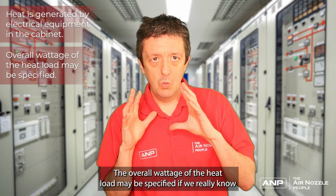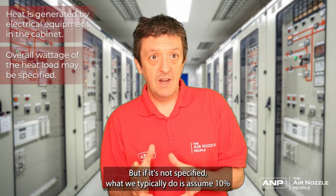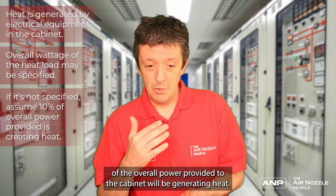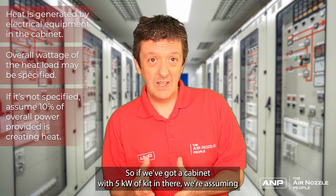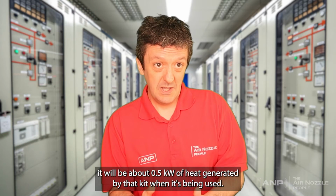The overall wattage of the heat load may be specified if we really know the equipment in there. But if it's not specified, what we typically do is assume 10% of the overall power provided to the cabinet will be generating heat. So if we've got a cabinet with 5 kilowatts of kit in there, we're assuming it'll be about 0.5 kilowatts of heat will be generated by that kit when it's being used.